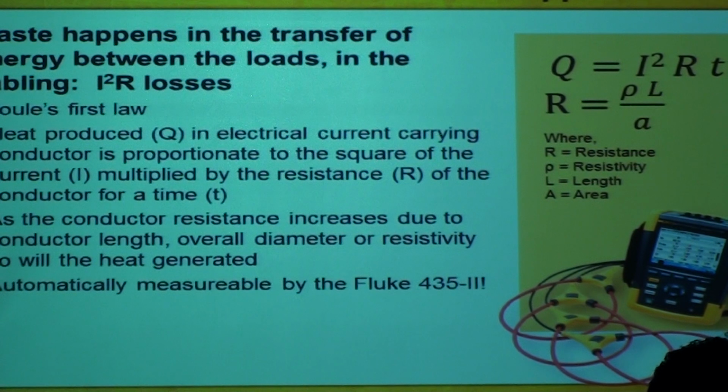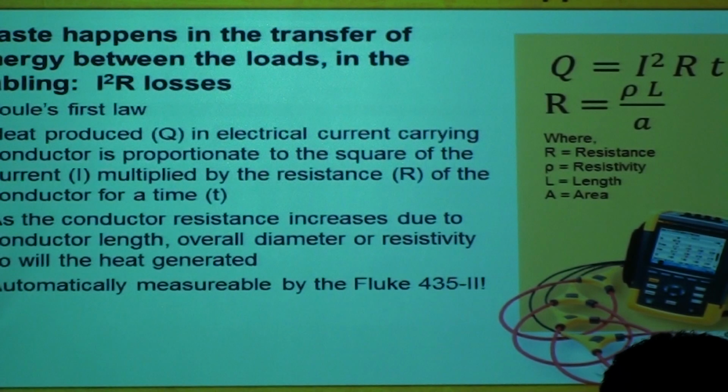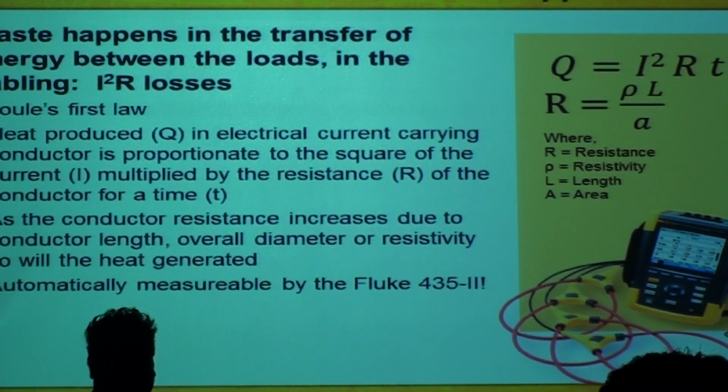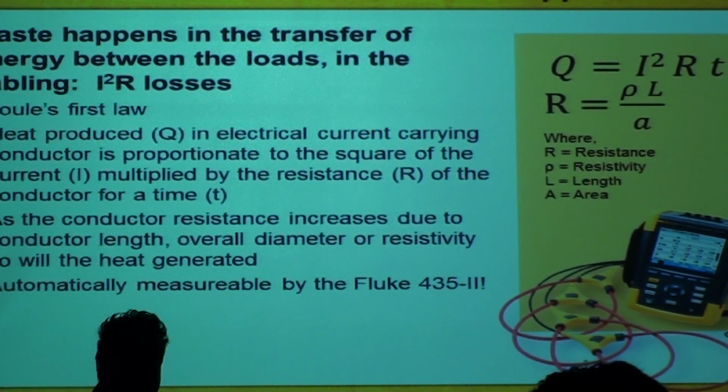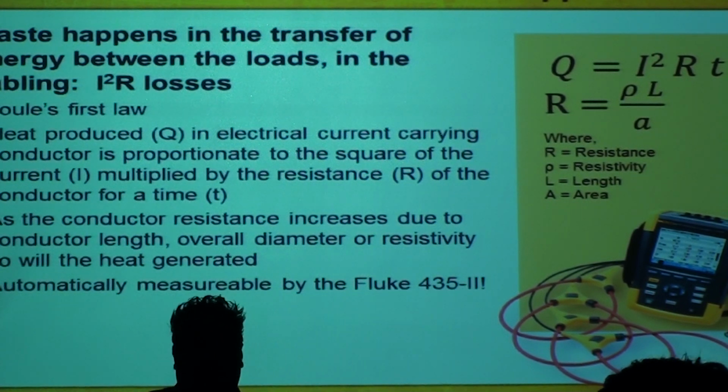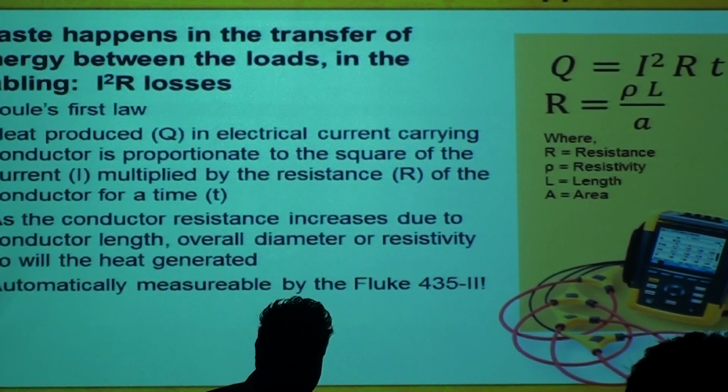So typically what happens is we have customers that hire consultants to measure energy waste. And this is how it's been done till we had some meters with us. Companies would hire consultants and say, listen, please come to our plant and identify the energy waste for us. So they would measure unbalance, they would measure harmonics, they would look at the reactive power.